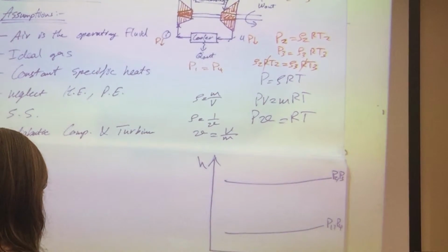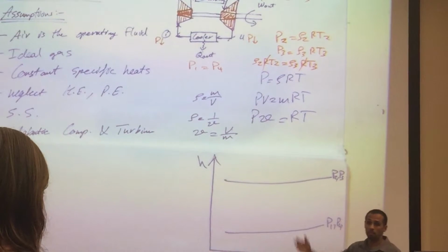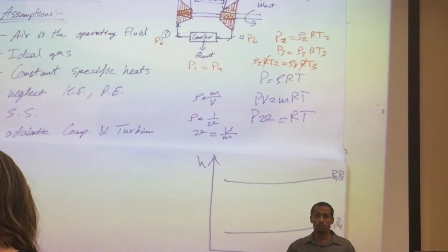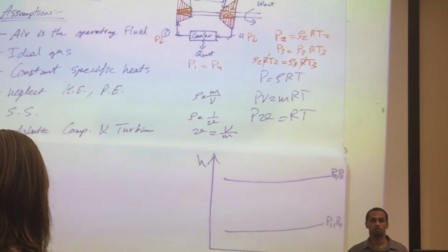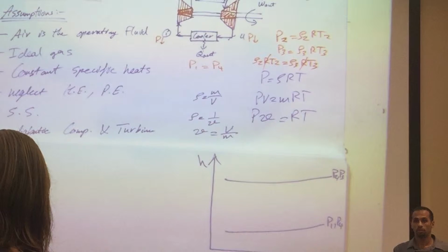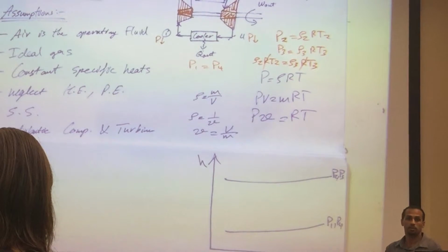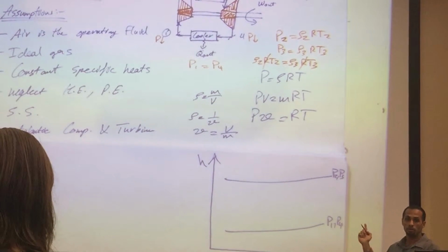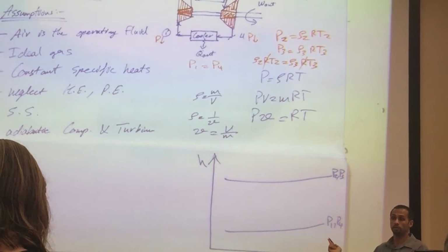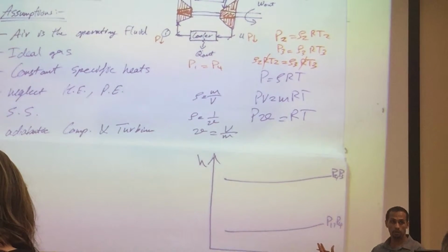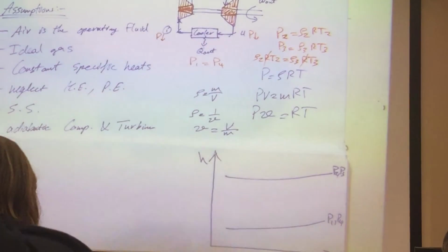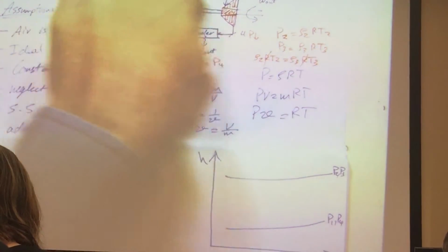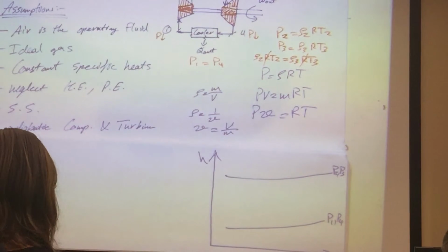So, if I'm adding heat and I'm expanding my flow, therefore my temperature is going to change. What your colleague brought up is a good point: what happens if my pressure is constant and my temperature is changing? What's going to happen? Density is going to change. Rho 2 is not equal to rho 3. Make sense? So that's sort of the pre-introductory to gas mixtures and reaction mixtures. So yes, density is going to change, and it changes quite a bit.